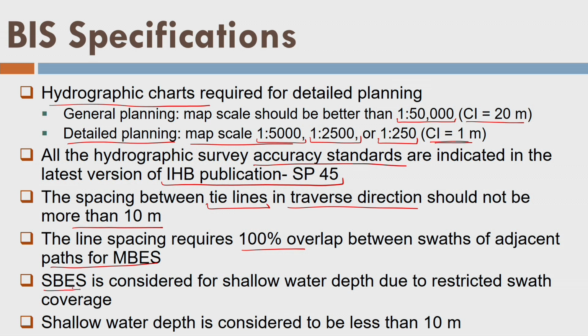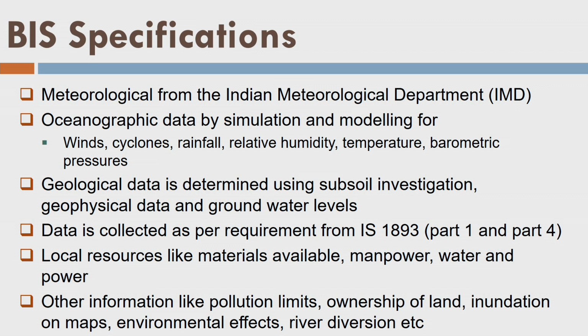So, single beam echo sounders are to be considered for shallow water depth. That means if the water depth is less than 10 meters, I can use single beam echo sounders. Now, in addition to that, the Indian standards also specify that meteorological data, oceanic data and geological data are to be collected as per this standard, then local resources and other information.